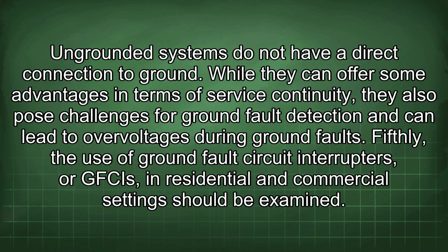Ungrounded systems do not have a direct connection to ground. While they can offer some advantages in terms of service continuity, they also pose challenges for ground fault detection and can lead to overvoltages during ground faults.